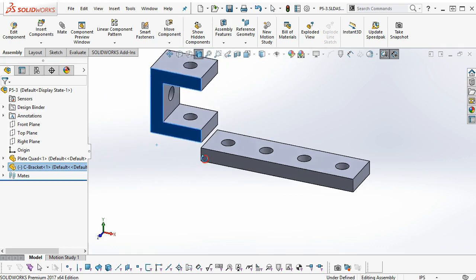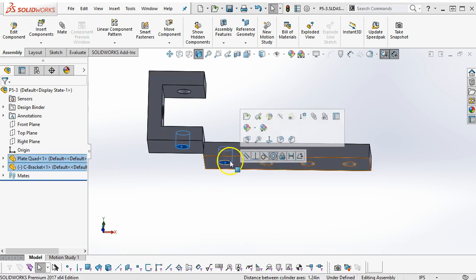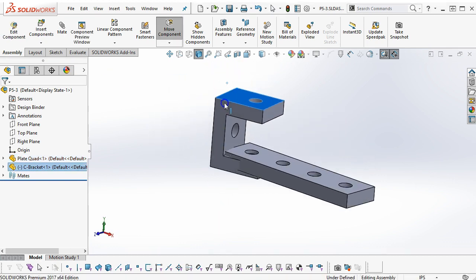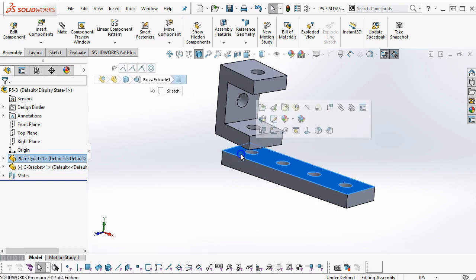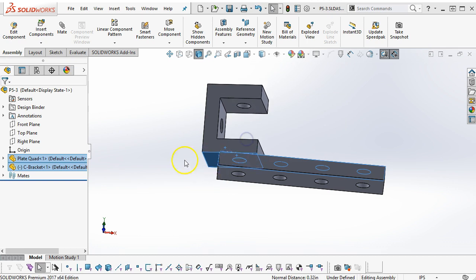I drop this in the work area, then it's free to move. All right, so select, Control Select as my other method, and the fastest workflow is going to take me to concentric. Right, the part's still able to move and allowed to interfere.